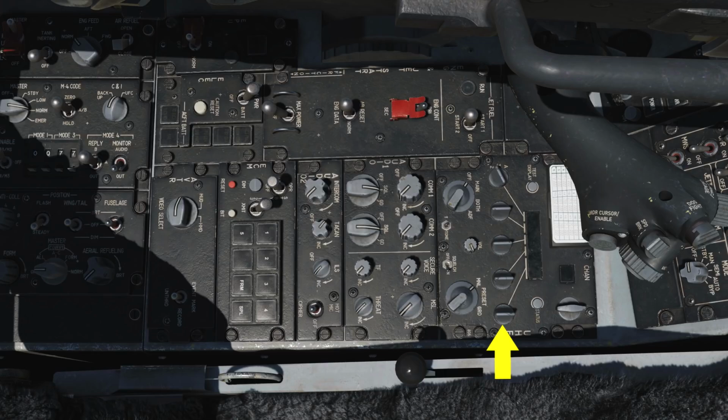In the center of the panel are controls to set the frequency with input dials and a display window. Along the bottom is a function knob to control radio power and mode, a tone signal button, the volume knob, squelch select, a mode select knob for manual, and preset guard frequency of 243 MHz. The Audio 1 panel controls power and volume to both radios, COM1 and COM2, and both radios have settings to disable squelch, enable squelch, and guard settings.